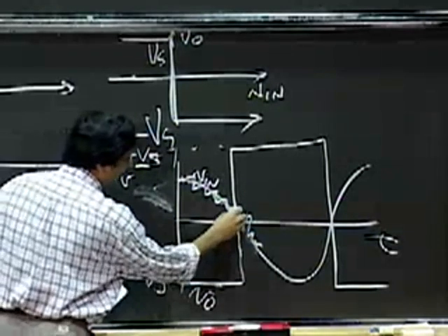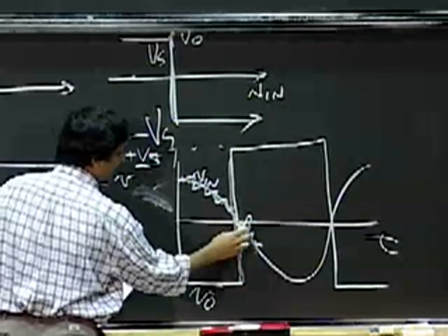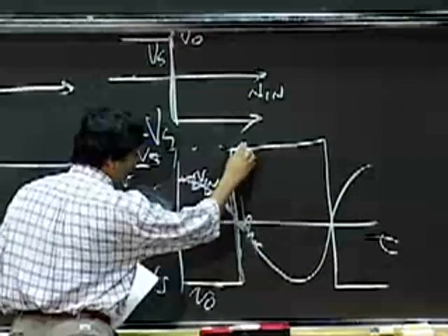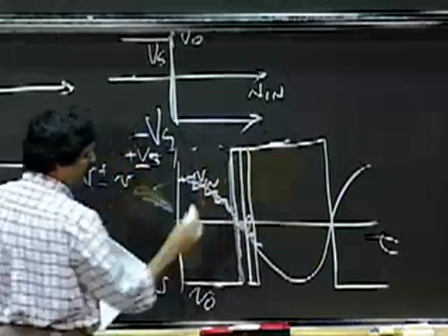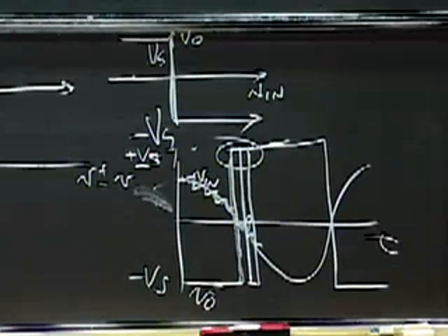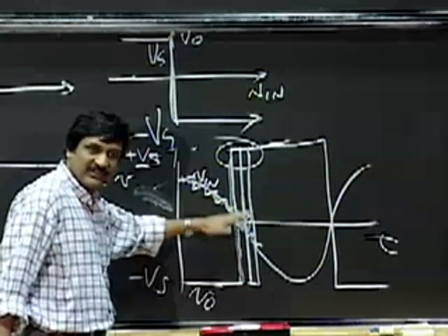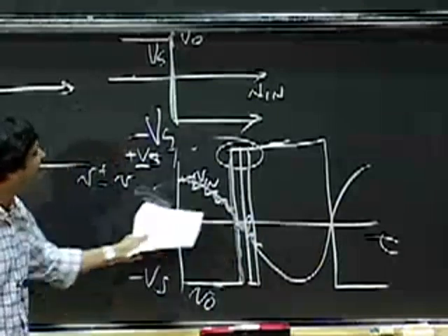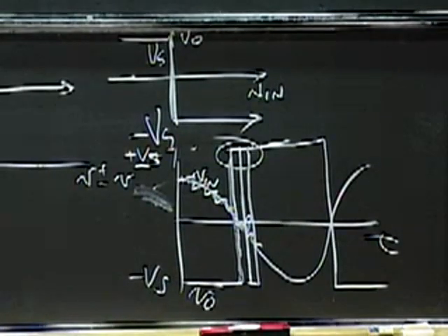So what happens is that at this point, where the value goes negative, I do bump up. But when, for a second, I have my input going above 0 again, this output comes down again, and out here it goes up again. So I get this nasty behavior at the point where the input is around 0. When the input is meandering around 0 because of noise, I get a huge amount of up and down glitches on the output. Okay, that's not very nice. And we'll do a little circuit that attempts to fix that little problem.